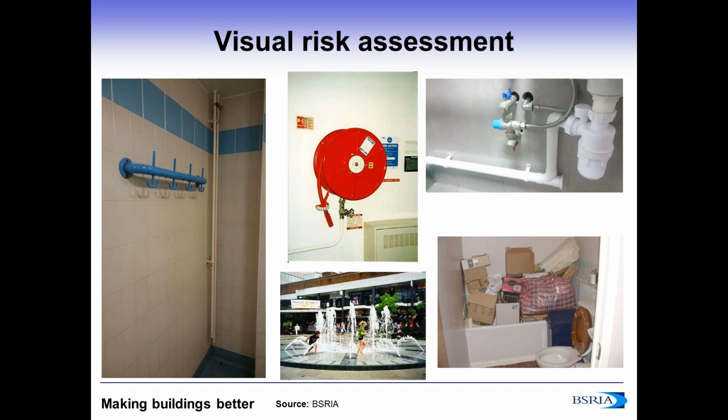The top photo on the right-hand side is a thermostatic mixing valve under a sink. There is a relatively short dead leg, and the tap is frequently used, about once every hour on an average day. Therefore, the risk is minimum. The bottom photo on the right is showing an inaccessible bathtub and shower. These are possible reservoirs for bacterial growth, not being accessible for cleaning or maintaining.